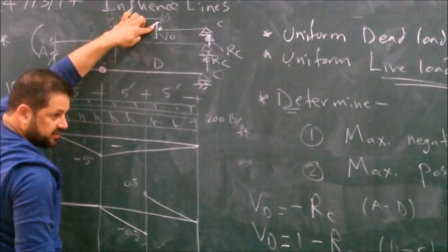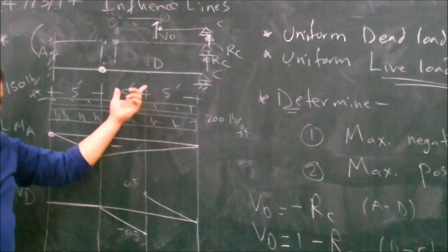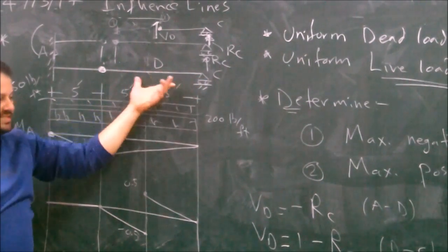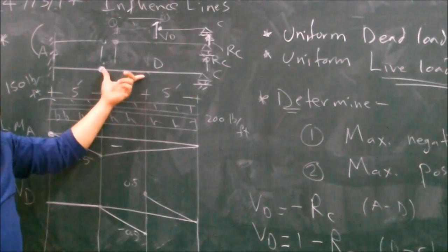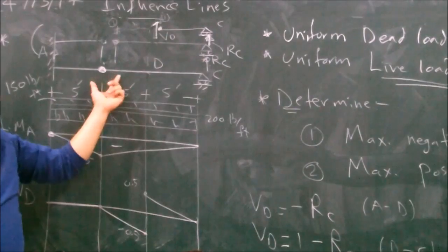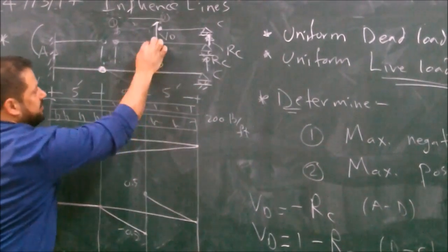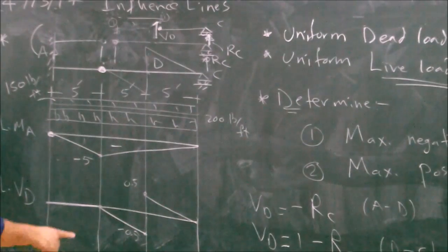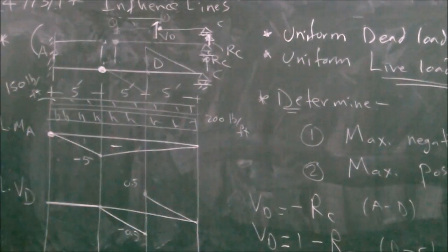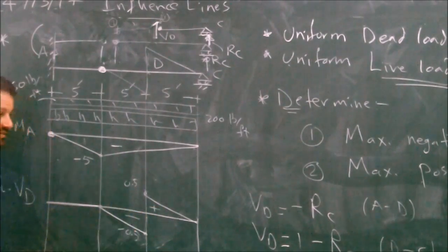Didn't I tell you once? The shear at D for a simply supported segment equals this over the span, 5 over 10. I told you it will go this way, up, then this. Minus 0.5, 0. So this is a positive shear, and this is a negative shear.